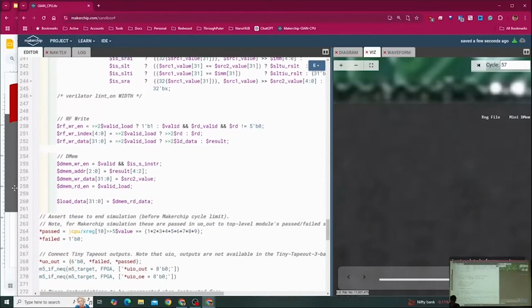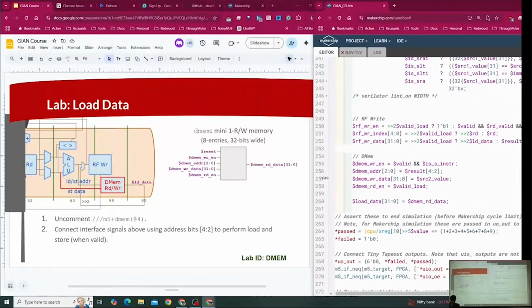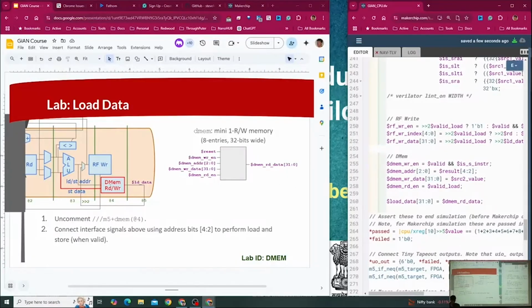So what I want to implement is this picture. The memory is in stage 4. All of my inputs are ready in stage 3. So assigning the inputs in stage 3 is fine. But my output from the memory is apparently not available in stage 3, which from this diagram makes sense.